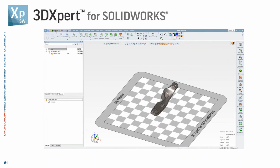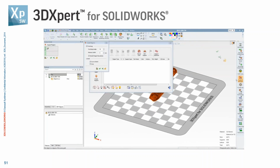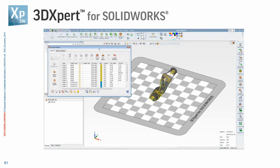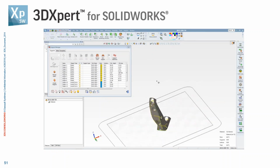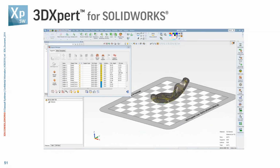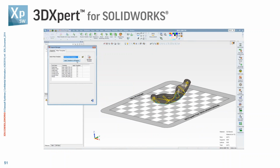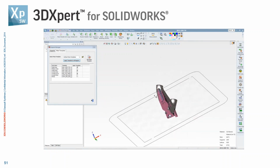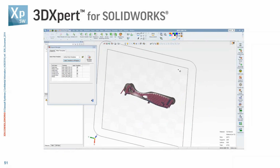Now, we're going to need some support underneath here. It's floating in the air. It's kind of a very organic shape here. So we go into the support manager, and then we can see how different supports are needed on the faces there. I think we have 35 different support types with different settings. You can say these are templates, to create some nice support for the model.